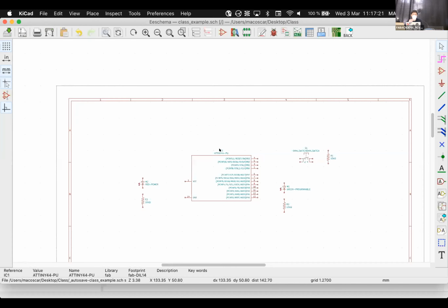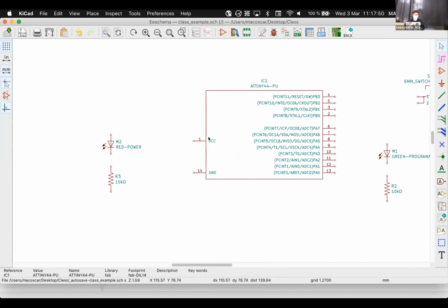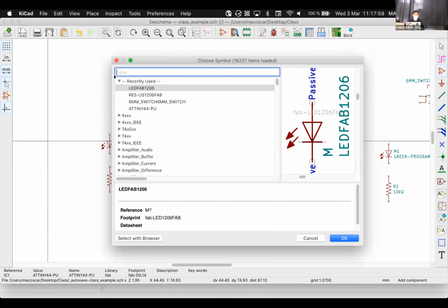Before we go into starting wiring, I'm just gonna add two more components. Well, actually one more component and two symbols. I don't expect you to remember, but we talked a little bit about capacitors two weeks ago, and that one of the purposes for the capacitors was to filter the power input of our electronics. So it's very normal, and you'll see this, and you'll repeat it until you get bored, to add this circuit in the power input. You see here that you have VCC and ground. To add the circuit that I'm just going to show you, which basically adds a ceramic capacitor in the input.